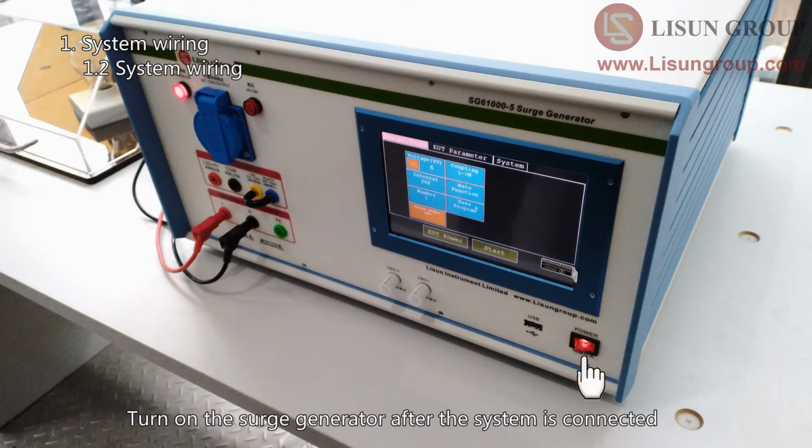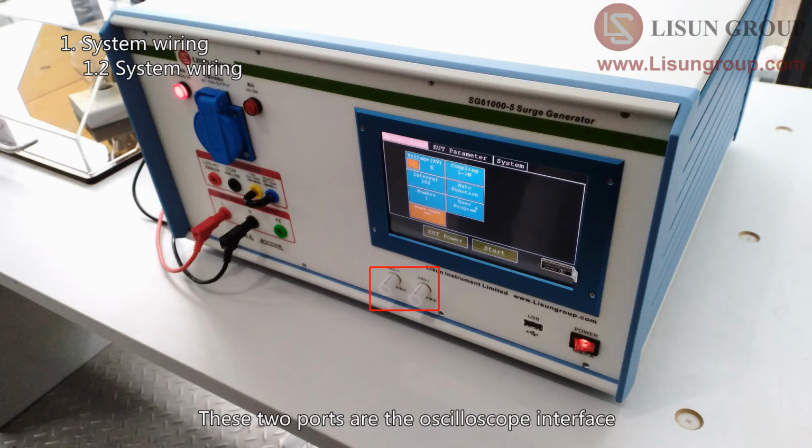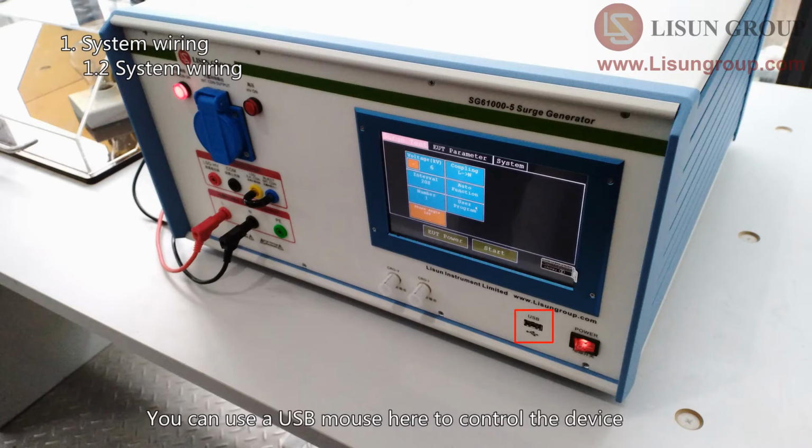Turn on the surge generator after the system is connected. These 2 ports are the oscilloscope interface. Connect the oscilloscope here if you want to view the surge voltage and current waveform. You can use a USB mouse here to control the device. A pen drive can also be used here to export the test data.